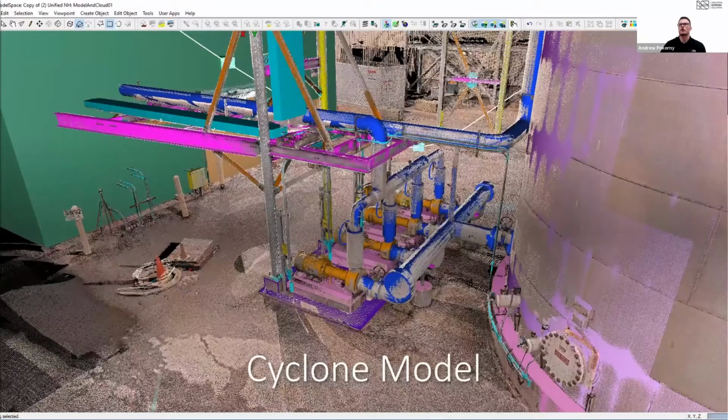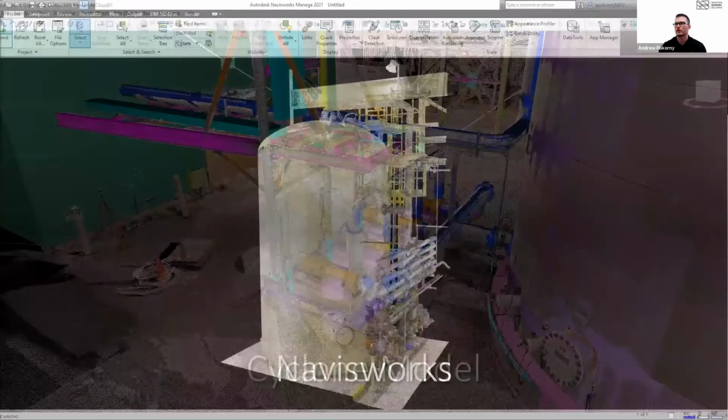One of our primary modeling locations is going to be directly in Cyclone. When you're working with the full point cloud as it was seen from the scanner, instead of down the line after a couple of exports, you don't have any of that decimation of the cloud, and you can really get in and get some details that you may not see down the line. So that's a great tool for us. There's a lot to learn. It's the Unix of modeling software, where it's incredibly powerful when you know it, but it can be very difficult to learn. But once you know it, it's a great tool to work with, and that's one we really like to use.